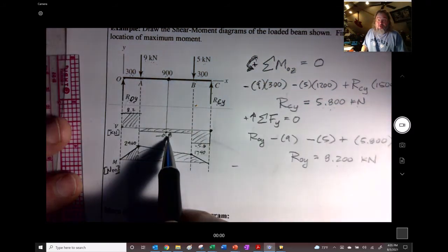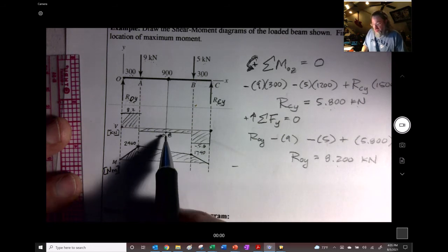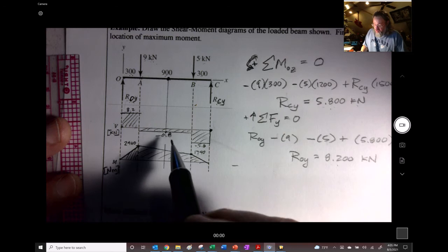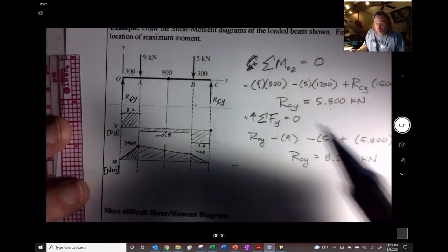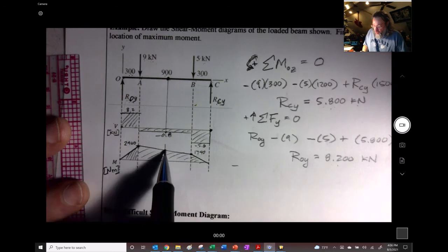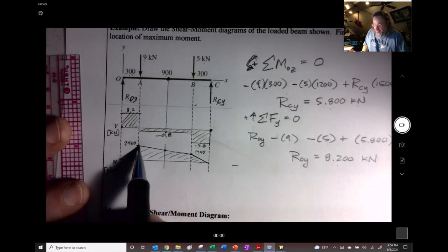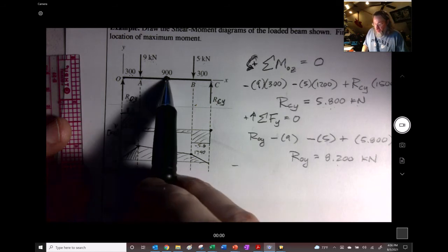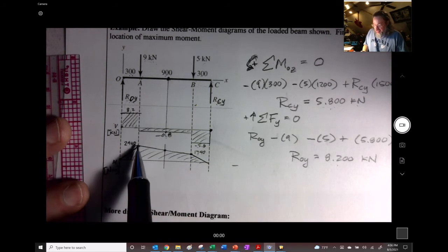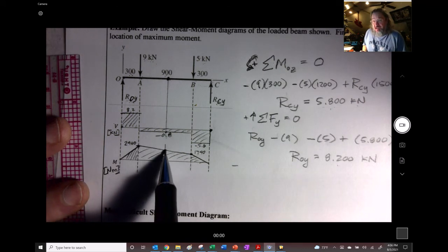And we'll say, like right there, the shear is 800 newtons, right? Because this is 0.8 kilonewtons, right? And it's indicating that it's a downward shear, if we care about the direction. And then right here, we could go ahead and figure out what that value is by multiplying 0.8 times this distance, which is going to be, what, 450, and then subtracting it from the 2,460, and then we'd be able to find out what the moment is.